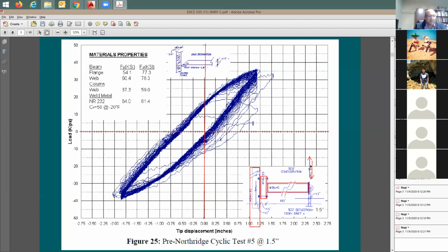And then after that, you're going to stop the equipment, like the hydraulic ram, which is the actuator that you apply the force with. Now we're going to start to push it down. Now we start to push it down, it's going to be going down here. It's going to start to yield at this point, and then you're going to be going back and forth till you have failure. Now, once you have the failure here, what happened? You have a break in the welding connection, because this welding connection is not good enough. So now the system stopped.